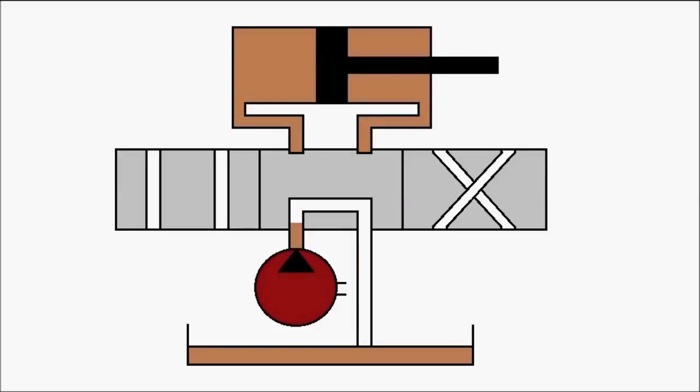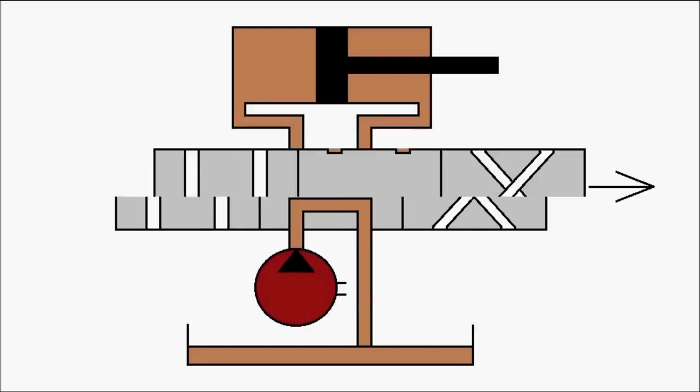In this position, the flow from the hydraulic pump, as the color indicates over there, goes directly back to the return line or towards the reservoir. So this is a neutral line. Here the flow is not connected towards the hydraulic ram, so work is not happening in the hydraulic ram at this point of time. And now let's move the direction control valve towards the right.